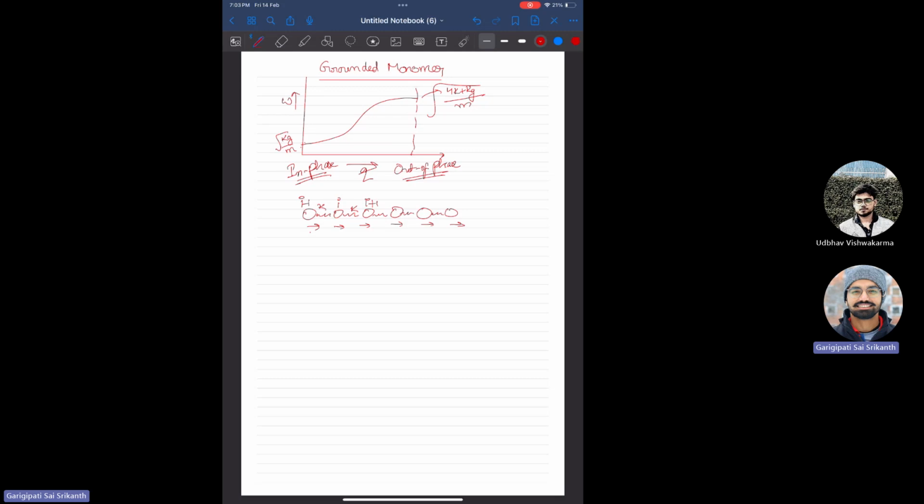If you see harmonics as an exchange of potential energy and kinetic energy, if nothing is going from kinetic to potential, then there are no harmonics essentially. So frequency is zero. It's a rigid body motion.